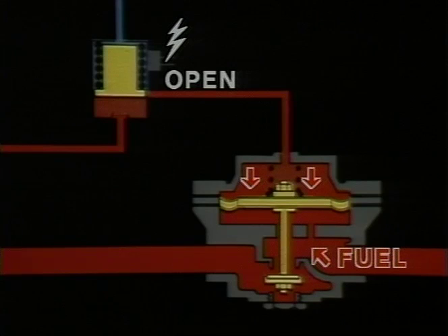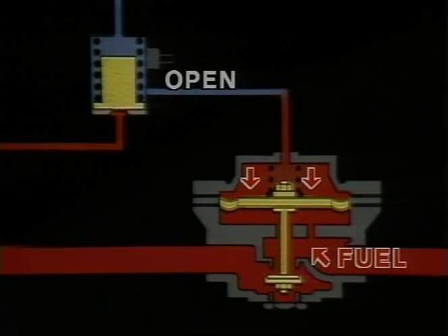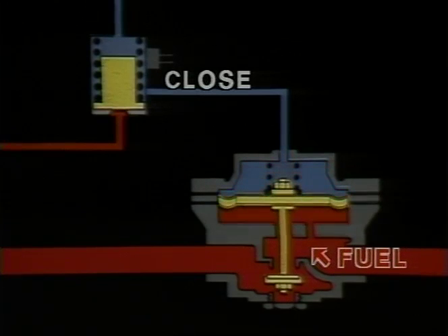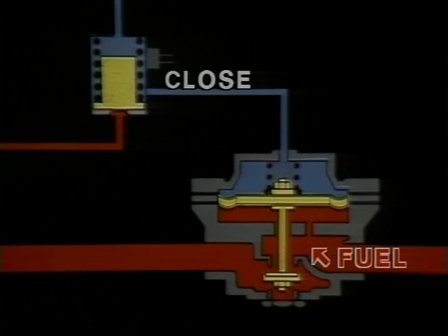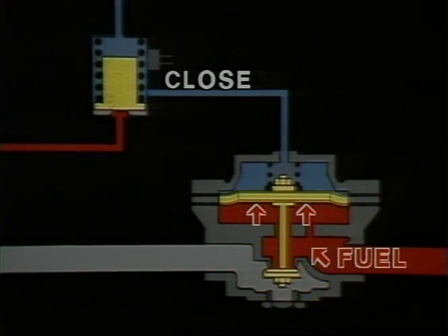Remember that when the stop switch is pressed, the DC signal to the pilot solenoid will be interrupted. The pressure side will close and the vent will open. So, the loss of pilot pressure to the control side of the valve diaphragm means that supply side pressure will overcome diaphragm spring pressure and the valve will close. In fact, the secondary valve will close when supply side gas pressure increases by 1 to 3 psig.